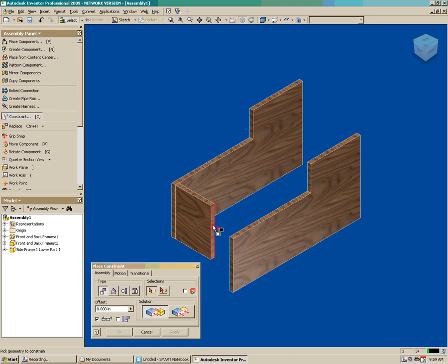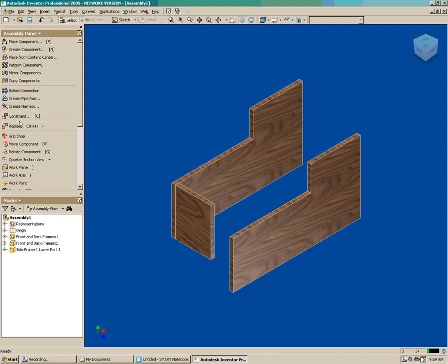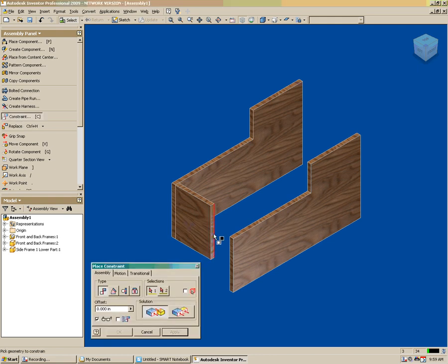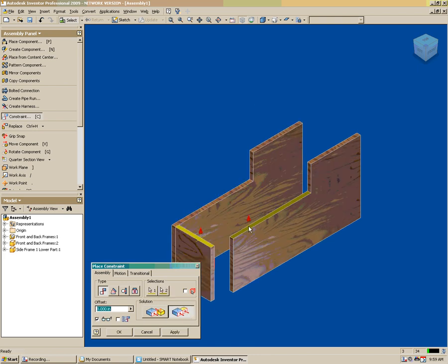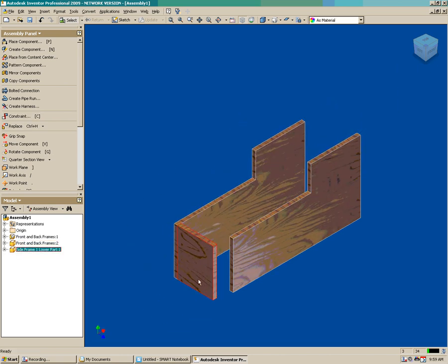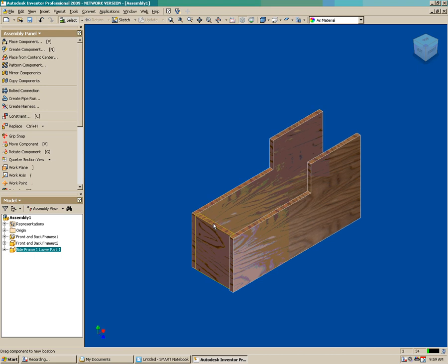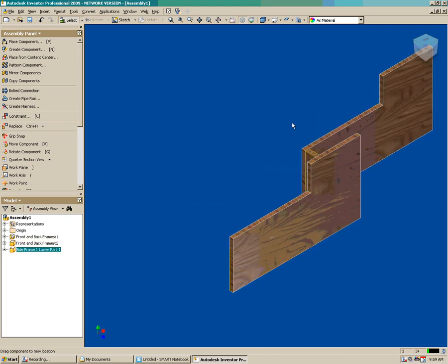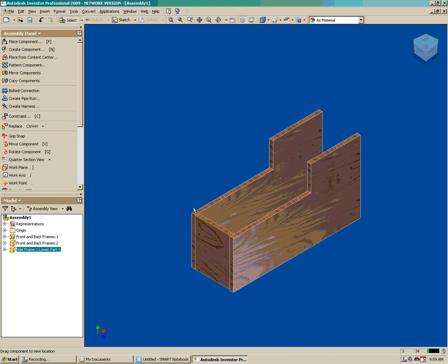Anyway, now I'm going to mate. I already did this mate command. You can't actually see the first command. Like, I'll show you what I mean by that. So now I'm going to flush this to this. And now I can see that there's a command. Why? Because I cannot move this up and down, because the flush made this level. Alright? So that's what I meant by after one command, there's no actual evidence that you did that command.